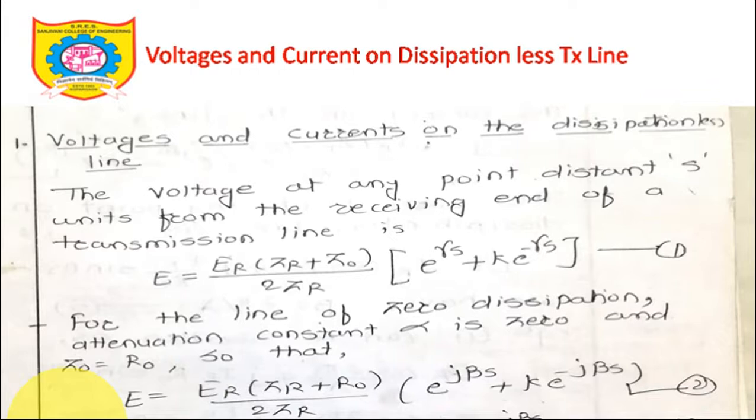So let's talk about this now: voltages and current on a dissipationless line. We already know that for a dissipationless line alpha is equal to 0. Let's go back to certain expressions of the transmission line which we already studied, the value of the voltage. The voltage at any point, distance s from the receiving end of the transmission line, is given by E is equal to ER into (ZR plus Z0) divided by 2ZR, inside bracket e raised to gamma s plus k e raised to minus gamma s.